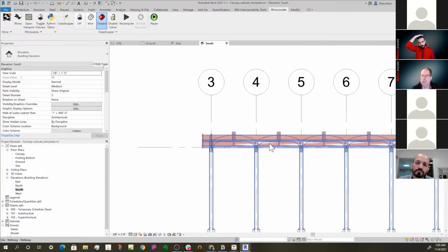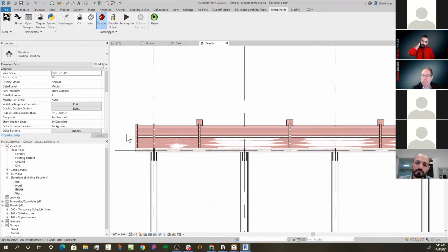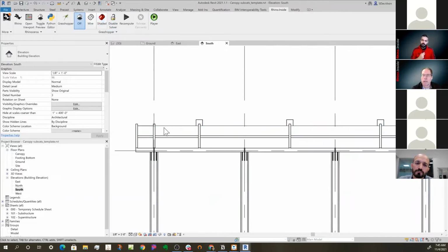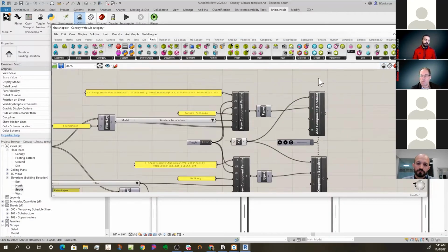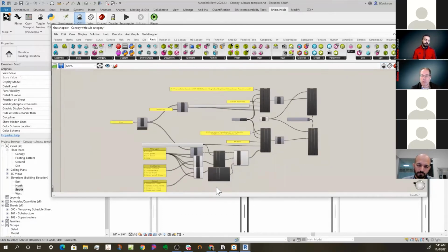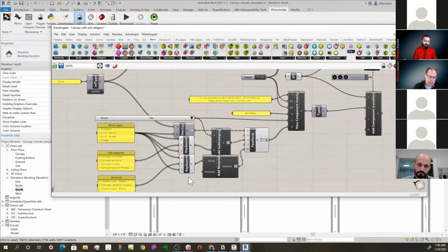And so if you want to change the way things get drawn in Revit, you need to be really familiar with how things are getting categorized. And so sometimes you want to send an object over that's complicated, but needs different, what they call subcategories, so that for each one of those sub-elements, I can change their graphics, what color they draw, whether they hatch, how they hatch, all those things.